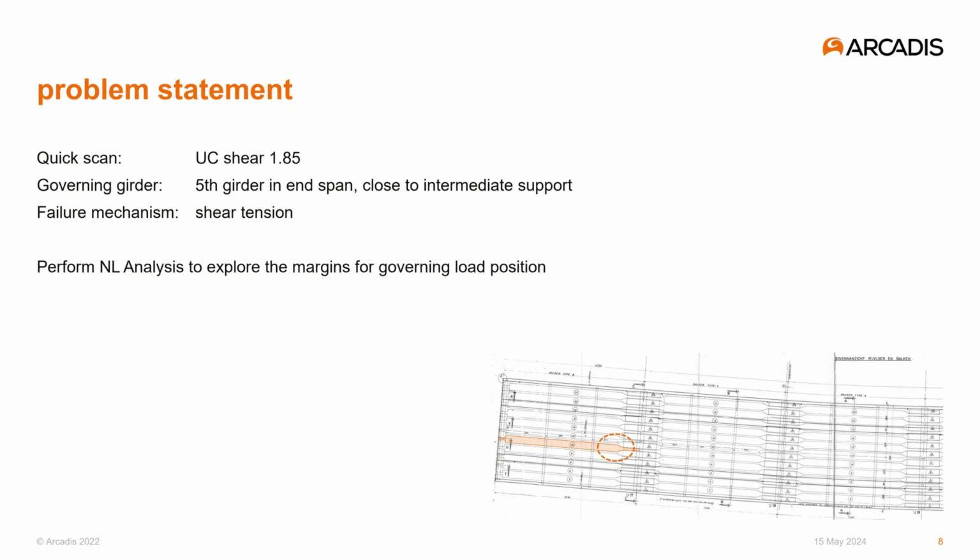Almost 20 years ago, the Dutch Road Authority started a huge campaign to reassess the structural safety of all their structures. The main reasons were the knowledge advances regarding shear strength and the associated change in design rules. Prior to 1974, shear strength was evaluated based on principal tensile stresses in the shear zone in the serviceability limit state. And for some situations, this approach proved to be too favorable. Starting from 1974, shear was evaluated based on shear stresses for the ultimate limit state, which yielded way less favorable results.